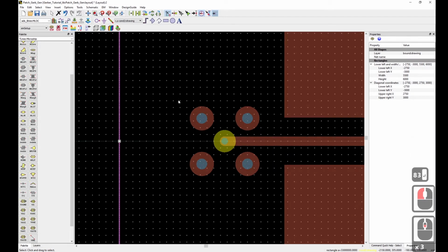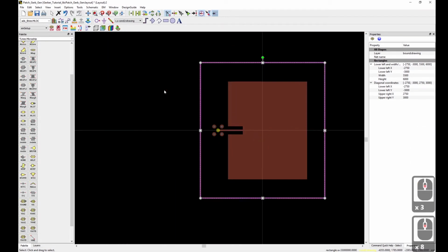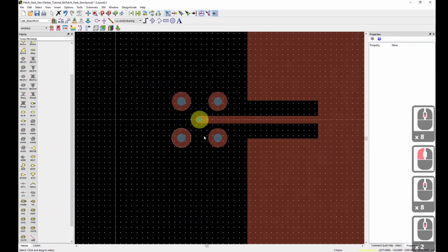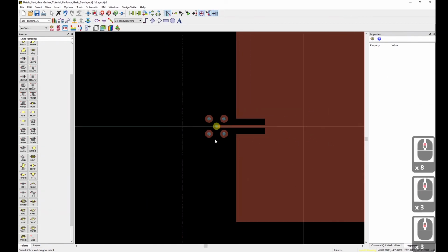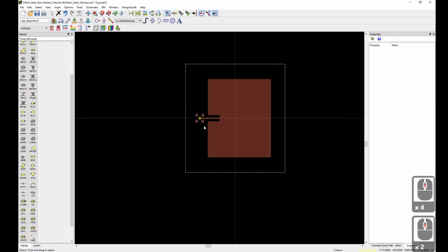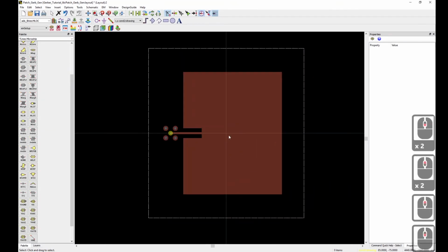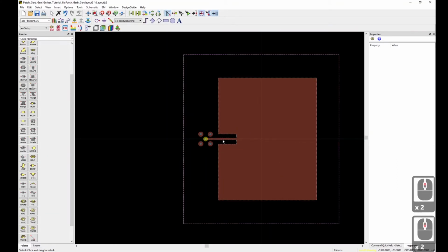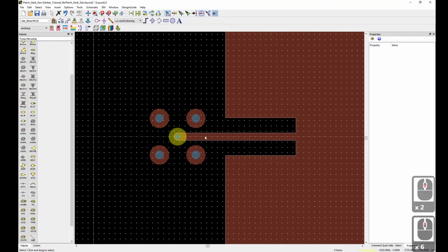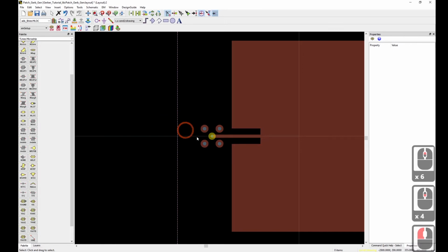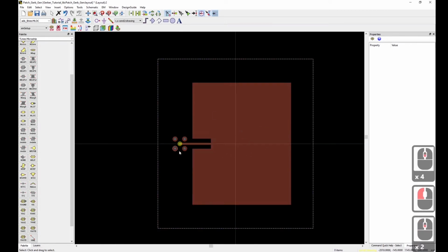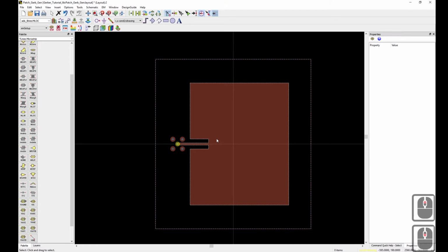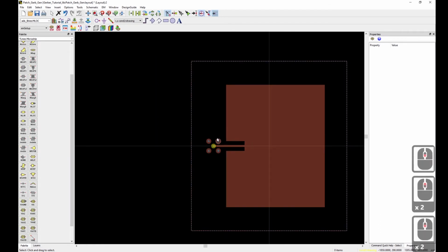And this is all that you really need for the patch design. You know, we've got our connector set up here. We've got our patch out on this side. The rest is basically going to be focused on the actual fabrication process. It's going to be specific to the fab process. So for the milling machine that we're going to be using, it's going to be a lot easier on the milling machine if we limit the area that the drill has to route. We don't want the drill to be rubbing out all of this area, or else we're going to go through the drill bits really quickly. So what we're going to do is sort of create a rub out region.